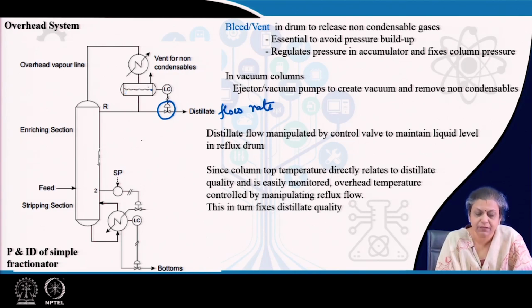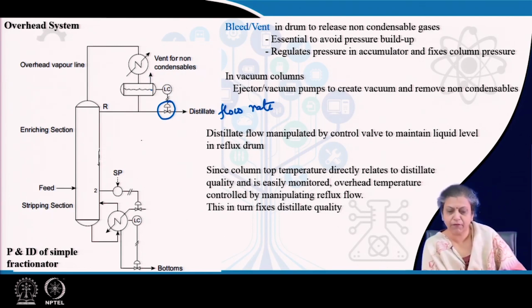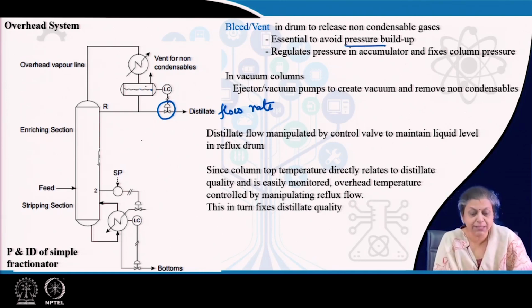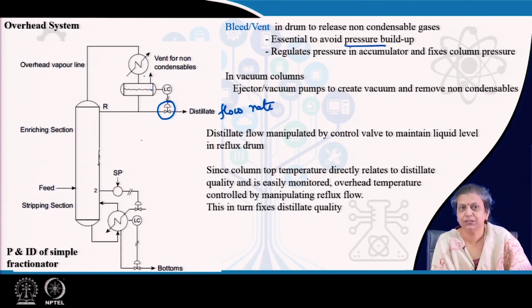So, momentarily we need to vent or to bleed out the gas from the reflux drum in order to avoid the pressure build up, right. Now, there is another very important purpose of this particular bleed that we use.